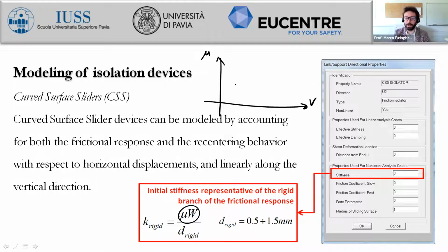And we have observed this dependency yesterday, and actually one general dependency is to consider, according also to one of the previous research works of Professor Michael Costantino, the friction coefficient as exponentially increasing for the first values of sliding velocity, and then a constant value is achieved asymptotically.